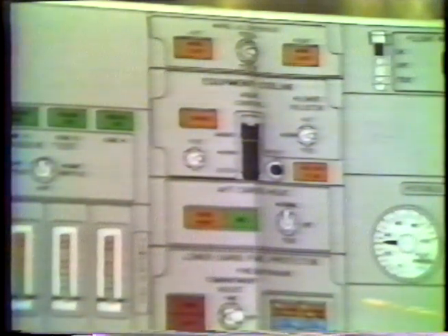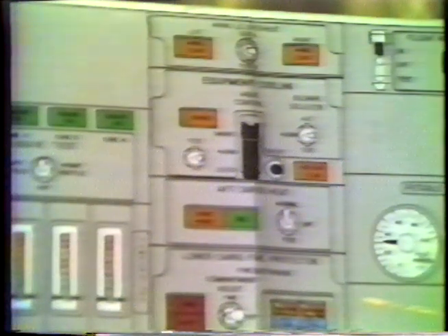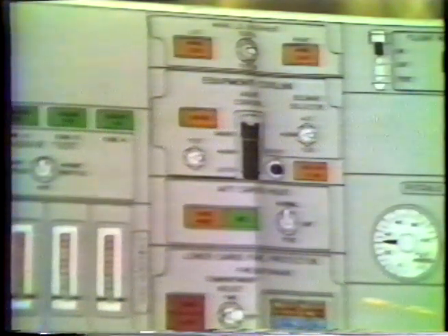To the left of it, we have an overheat. The overheat is set at a fairly low temperature, somewhere just slightly over 100 degrees. And as we well know at some of the sea level airports on a summer day, the temperature in the cargo hold could easily exceed 100 degrees, so it's not unusual to have the overheat light on the cockpit setup on a very hot day. It would be unusual to have it on a very cold day.